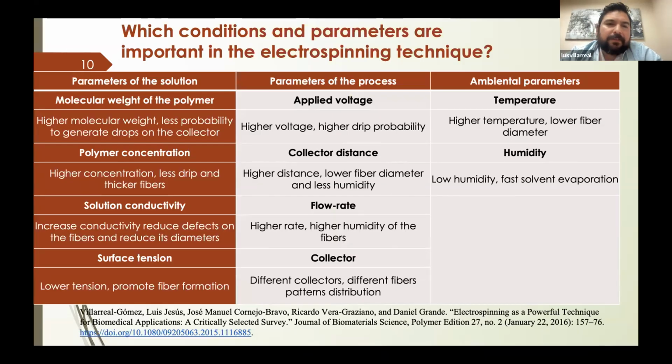To prepare nanofibers, you have to consider different parameters. You have to choose the adequate molecular weight. You have to prepare higher concentrations of the polymer solutions. You have to control the viscosity. The viscosity is an important parameter because high viscosity in the solution helps you to prepare the nanofibers. If you use a very dilute polymeric solution, you will have particles instead of nanofibers.